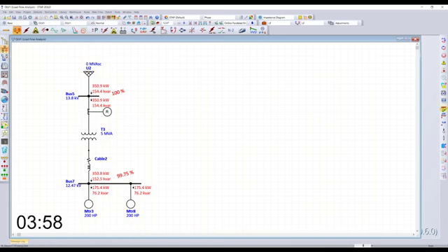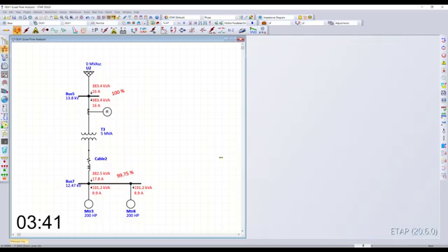The units are turned on, so you can essentially quickly toggle between them, or you can simply switch between different types of units, in this case kilowatt, volts, or percent for the voltage, or you can also turn on and see the kVA and the amps for the network. So our load flow is done.